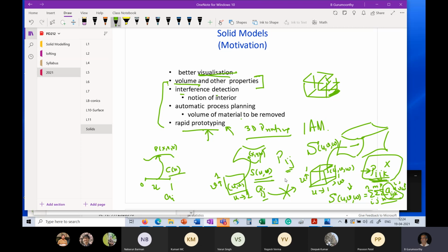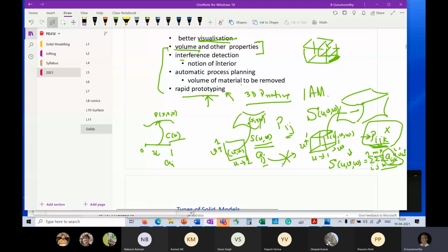The second bad thing, I hope, if you recollect, that's the last thing we did and we recapped it this morning, right? Which is that I have an inherent limitation in this kind of a mapping, that all my surfaces will be four-sided. Likewise, if I do this mapping, all my solids will be six-faced only. That is the nature of this mapping. I cannot go outside of this cube, and therefore my object will always be bounded by six faces, and therefore the only kind of solids I can create are either bricks or loaves of bread.